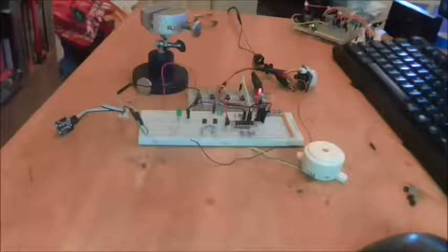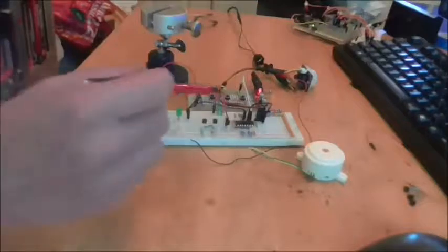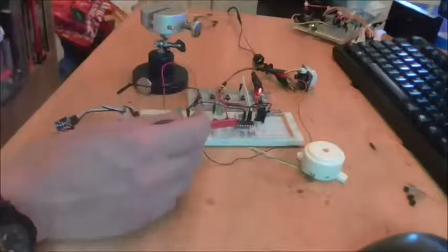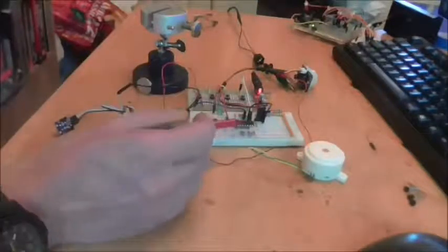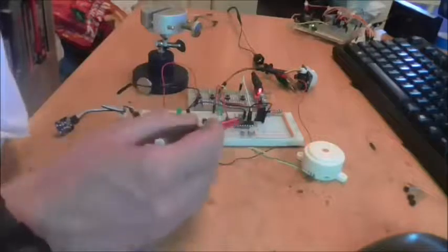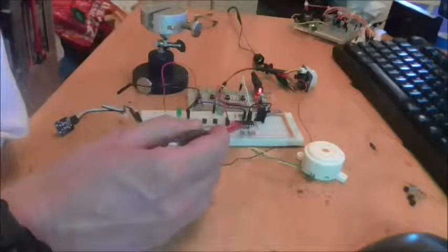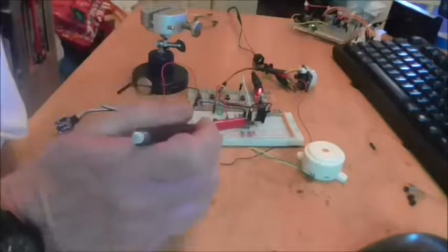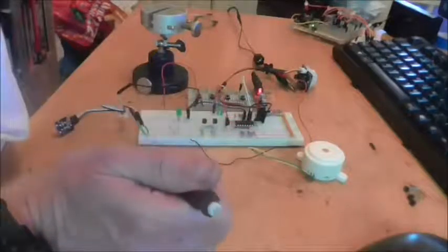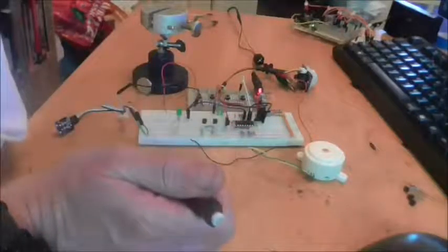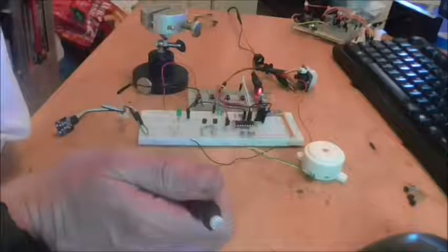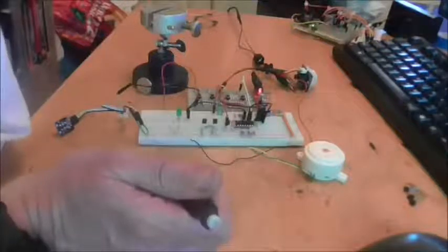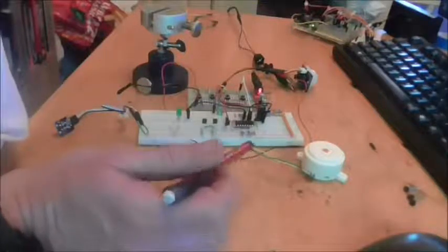The second lesson is that the chip here is working on combinational logic. And in combinational logic, we look at the inputs and that's all we care about. And the chip does the same. It looks at the inputs, that's all it cares about. If all three inputs are high, then the output is high too. If not, then the output will be low.